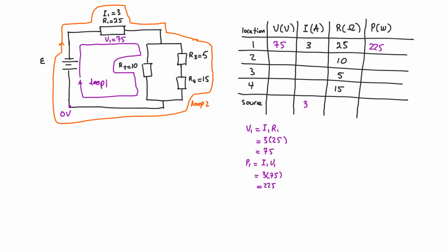So the energy they gain is going to equal the energy that they lose in the loads. So basically for loop number 1, the EMF, which is the energy from the source, is going to equal the voltage drop across resistor 1 plus the voltage drop across resistor 2. And we don't know the EMF value, so I'm going to keep it as E, which is going to equal V1, which is current 1 multiplied by resistance number 1. And the other one, I'm going to label this as I2, and this I'm going to label as I3, and this is going to be I1.